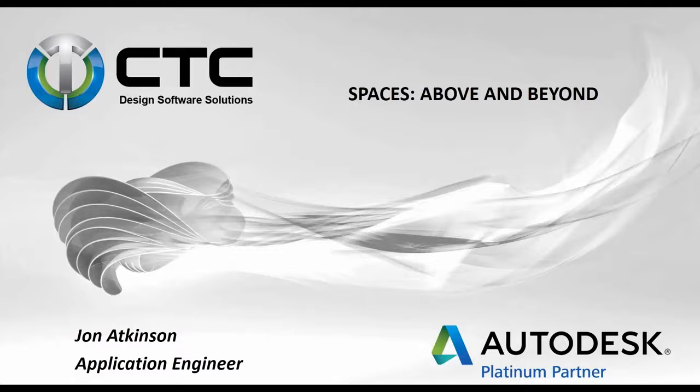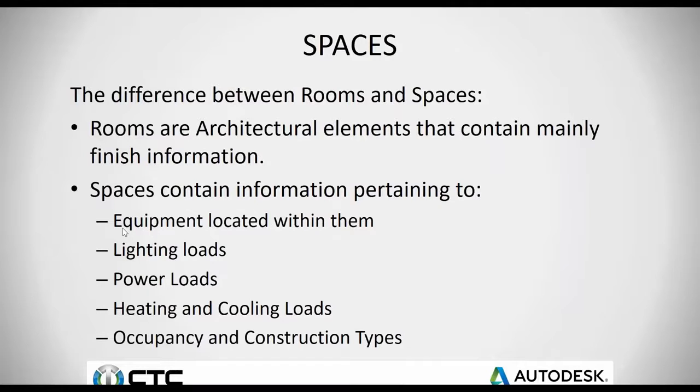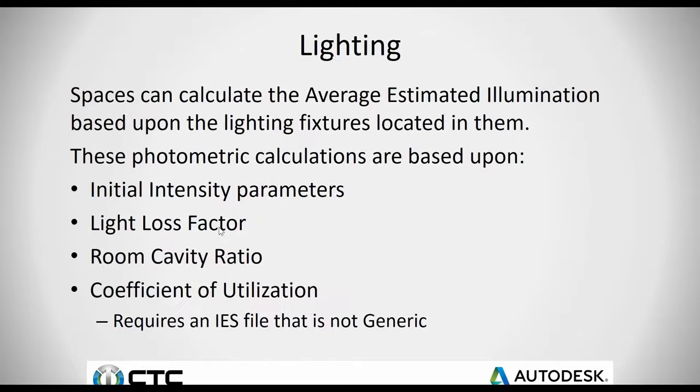Well, the difference between rooms and spaces: rooms are basically architectural. They contain finish information. They've got some area and volume in them. But spaces contain all the information pertaining to the equipment that is located within them. It'll give us lighting loads, power loads, heating and cooling, and we can define the occupancy and construction types for those spaces.